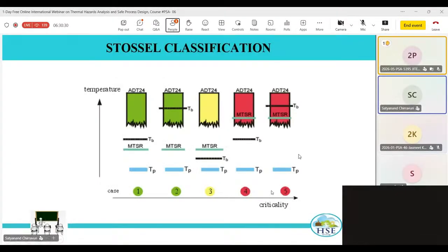So we are not supposed to hit the decomposition zone. Always effort should be to make sure that we never hit the decomposition zone, come what may, hook or crook. And the fifth is wherein straight away once cooling failure happens, it just enters a decomposition zone and decomposition happens. So this is a worst case.